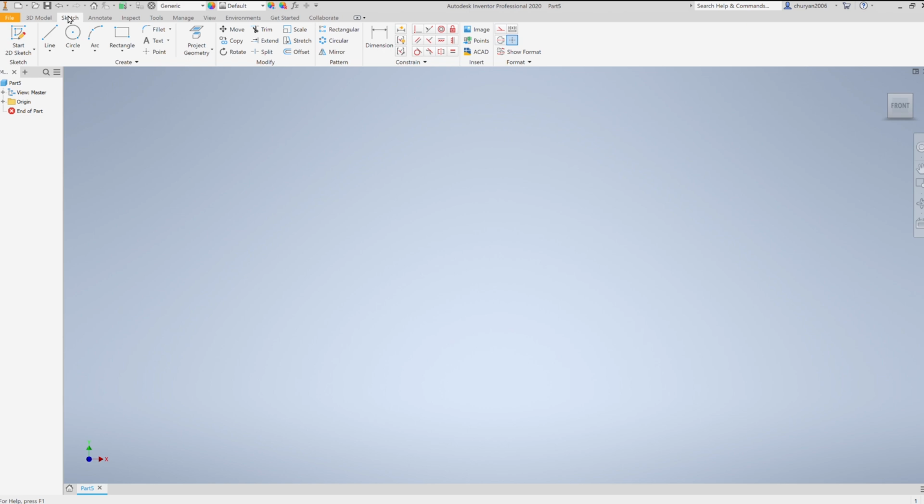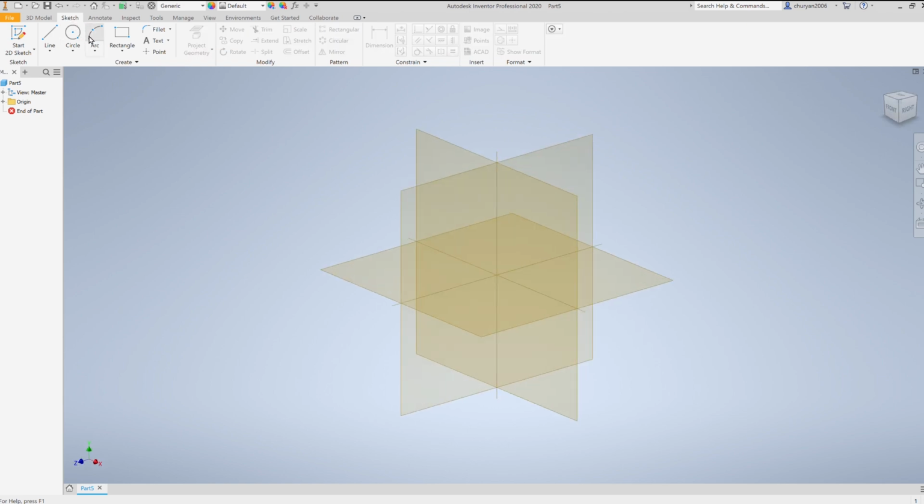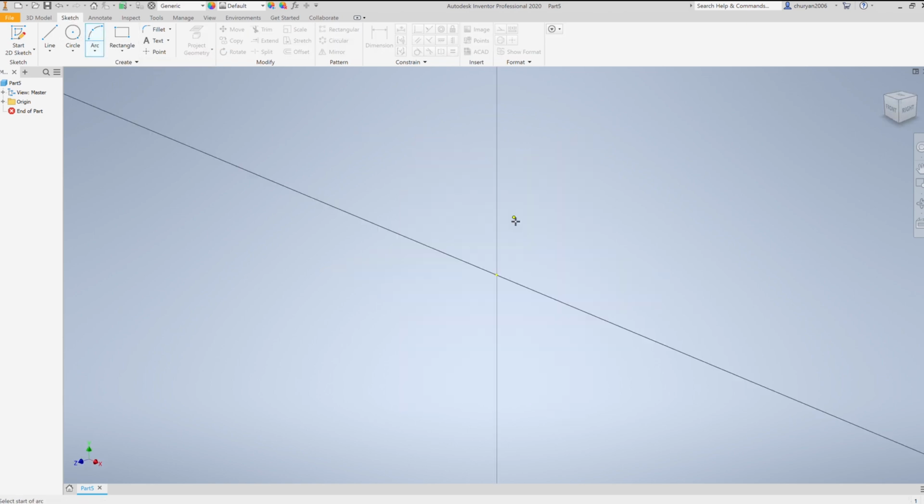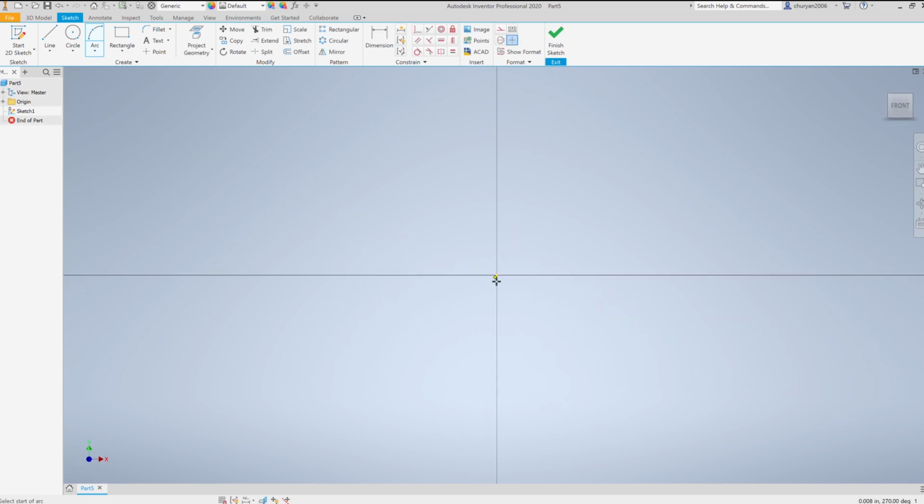Alright, and this is our third sketch that we'll be practicing today, and it'll be a crescent. To use an arc, you need 2 points, and to make the actual arc, you can either move your mouse up or down depending on how big of an arc you want it to be. I'll put a second arc since we're making a crescent, and we'll repeat the extrude process.